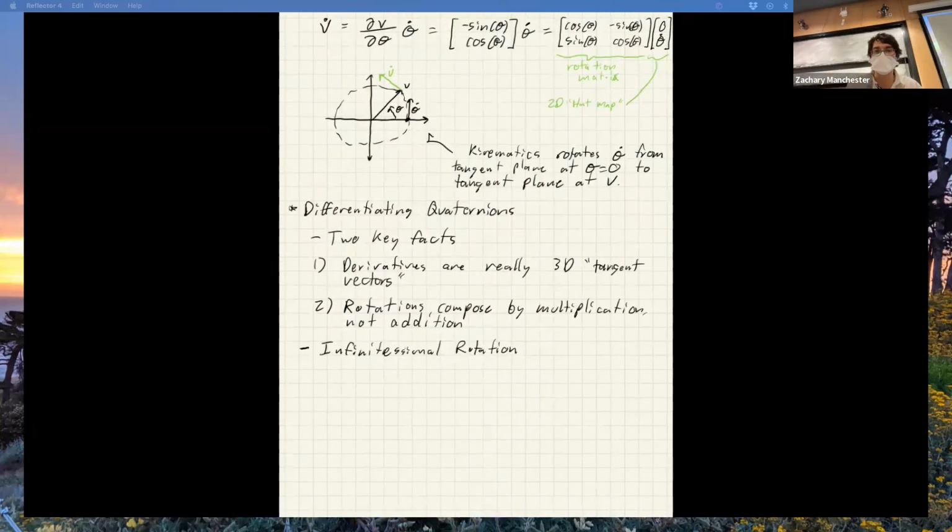We're going to talk about this idea of infinitesimal rotation. So I'm going to write this down as an infinitesimal, tiny delta quaternion, delta Q, a small rotation. If I write that down for some small angle, think about small angle approximation ideas, right? I'm going to get cos theta over 2 and then the axis of rotation times sine theta over 2, like we talked about last time. When we say small rotation, remember the axis is still a 3D unit vector. We're talking about small theta.